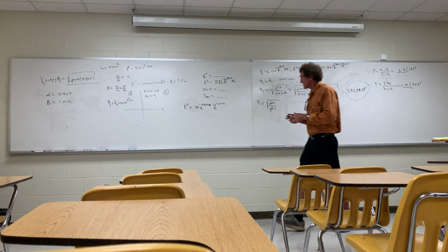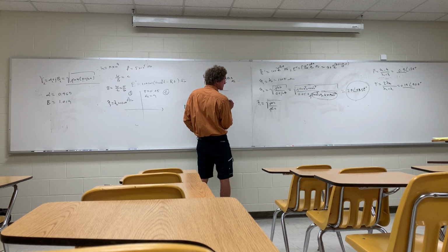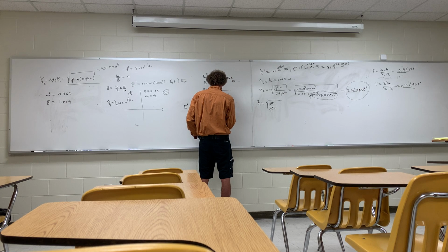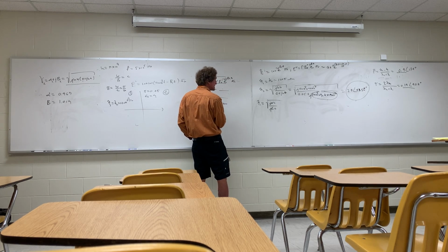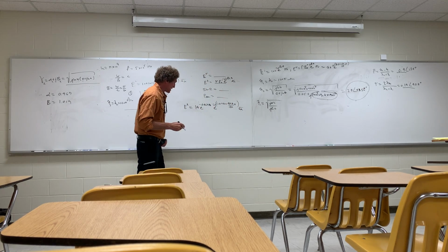It's gotta be in radians, and it would be added right here. So it would be that, and that's a positive angle, so there's a minus there. Whatever that is, 40.8 divided by 180 times pi, it has to be in radians, a_x, and that would be the transmitted field in the phasor domain.